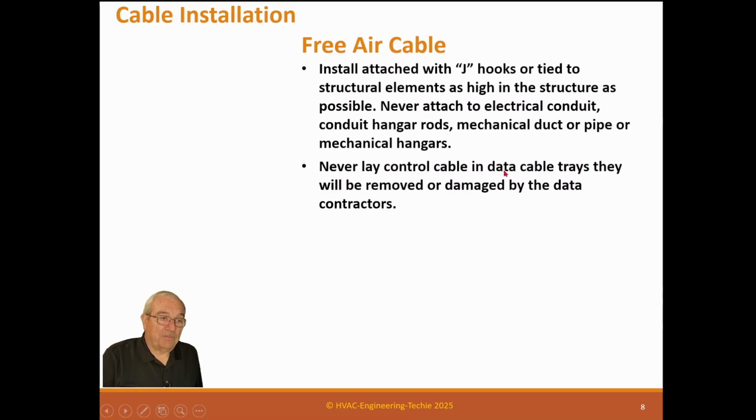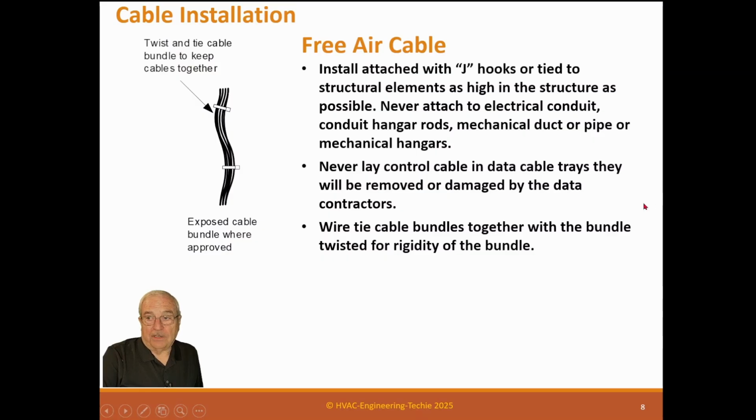Even sometimes we've had people try to wire tie to the outside of the cable tray. Don't do it, because they'll still cut it out. It's very, very frustrating. Another thing about cabling contractors, many times they're in there after the contractor's done. So there's no one there to police what he does to your cables. So just be safe. Don't put them in a cable tray.